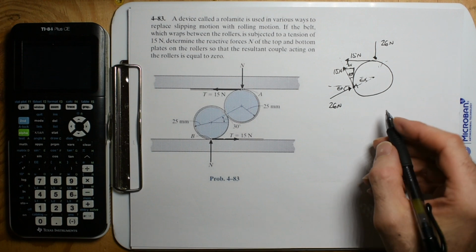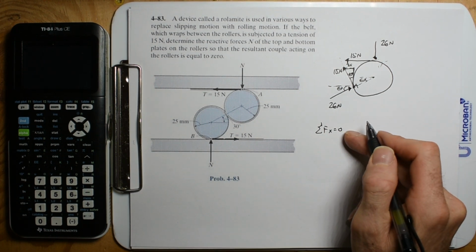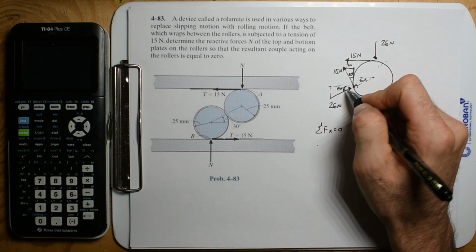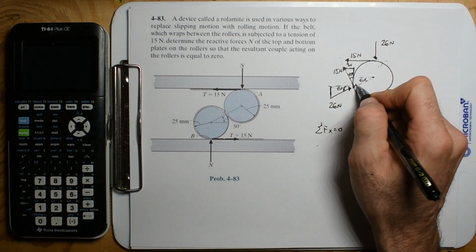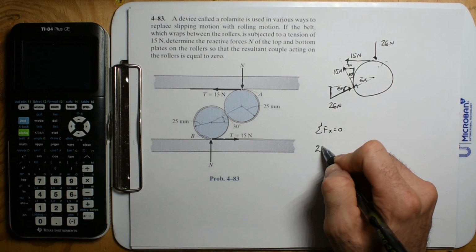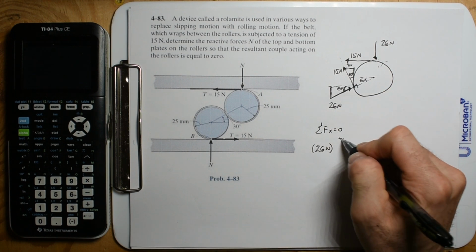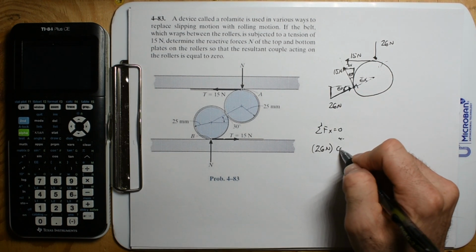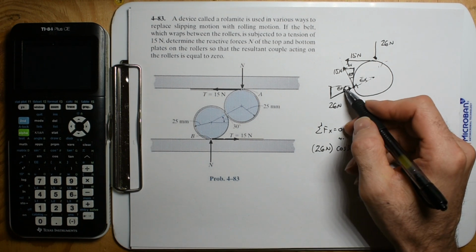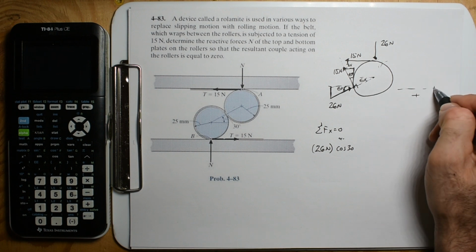Cool. So we're going to sum the forces in the x direction. That's going to be 0. So we're going to have this one. If this is the angle, sun is shining. This is the sine component. This is the cosine component. If this is the hypotenuse, it's the larger number. We need to take that 26 newtons and multiply it by a smaller number, that fraction. That's the cosine. Cosine of 30. And so we have 26 cosine 30, and that's going to be in the positive x direction.